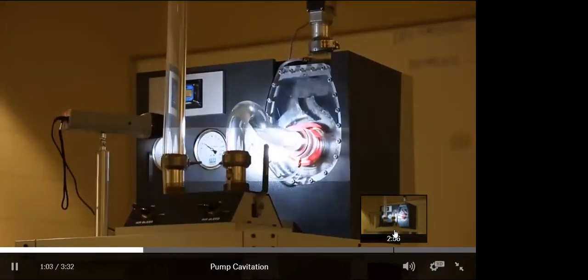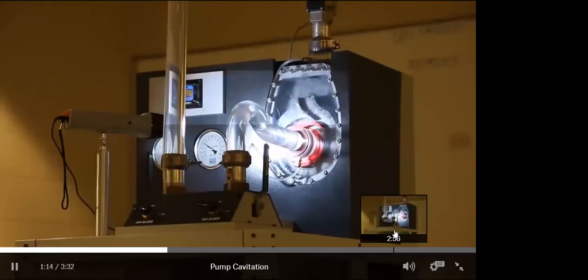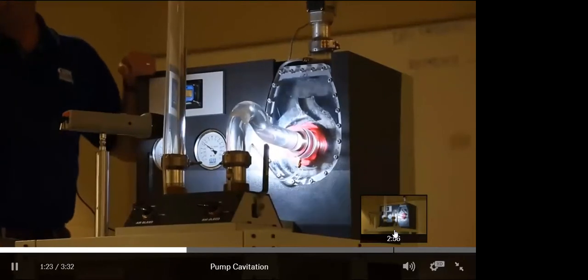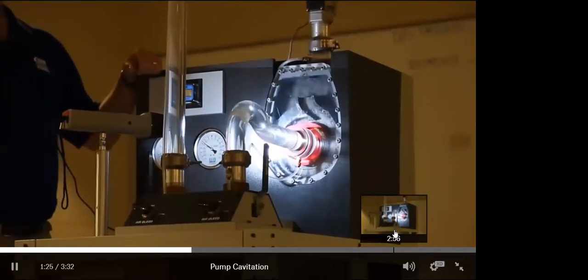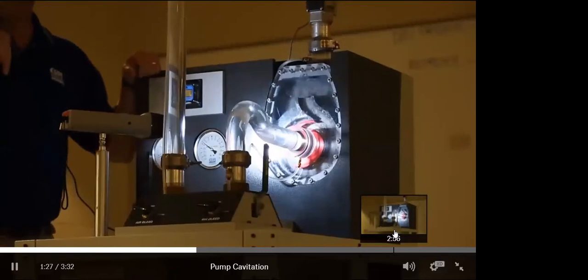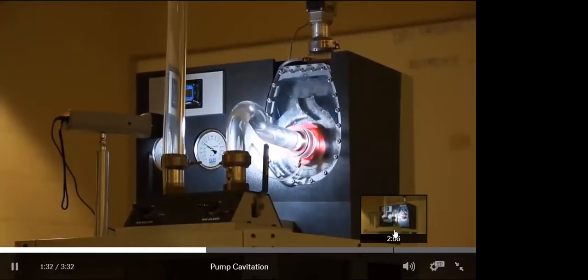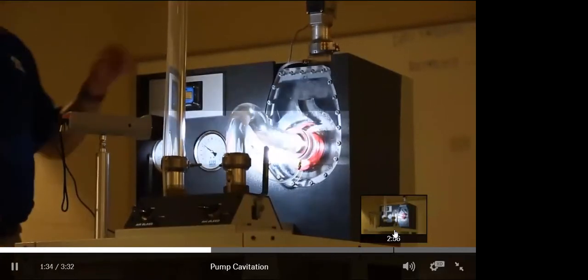There's two ways you can boil water, right? Take a pot of water, put it on the stove, turn on the heat, 212 degrees Fahrenheit, the water starts to boil, you've got steam coming up off of it, okay? The other way you can boil water is by lowering its pressure. The way we lower the pressure of the water is by increasing the velocity. As the velocity of the liquid goes up, the pressure goes down, and the liquid can no longer stay in a liquid state. It's going to flash to vapor. And that's what we're doing.